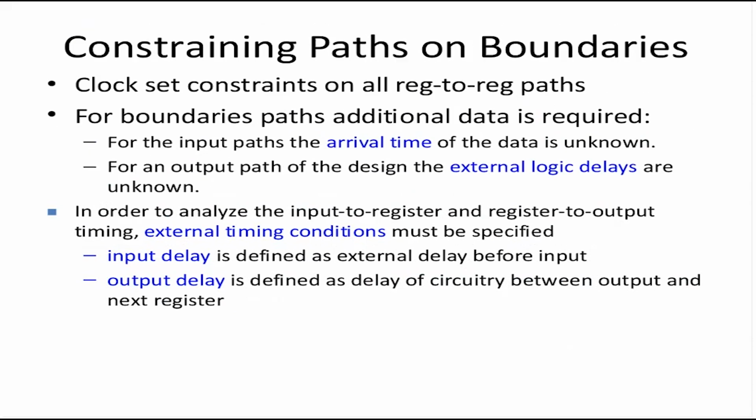So for the boundary, additional data is required. One thing required is the clock. For the input ports, the arrival time of the data is unknown. For the output port, the external logic delay is unknown. In order to analyze the input to register and register to output timing, external timing conditions must be specified.